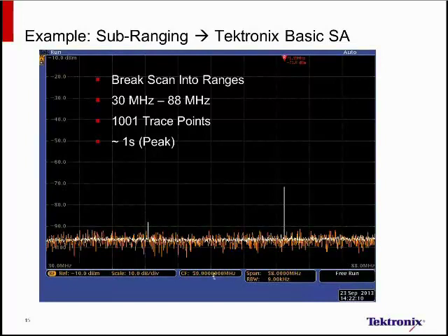When we have automated software, as you saw on the previous 2 slides, we could store the information in those tables and then do a table comparison afterwards to subtract out those frequencies we knew were from an off-air source. The rule of thumb here, though, is be careful. Fully characterize your ambient environment so that you can do an accurate job of assessing which products are coming from the device under test and which products are coming from the ether.